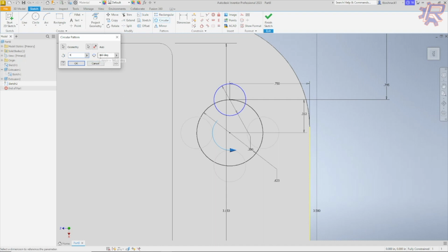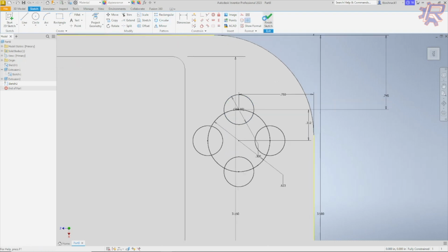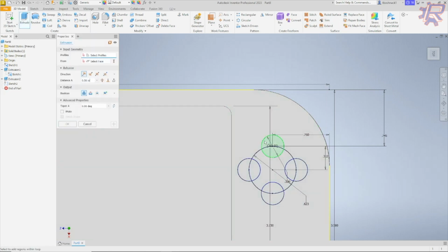And this is over 360 degrees. It's the full circle that it's projecting it around. You make this less to 180, and it'll just be in this half circle. Let's make it up to 360. Now that we have all our buttons, let's just quickly extrude them to 0.05, just a little bit.